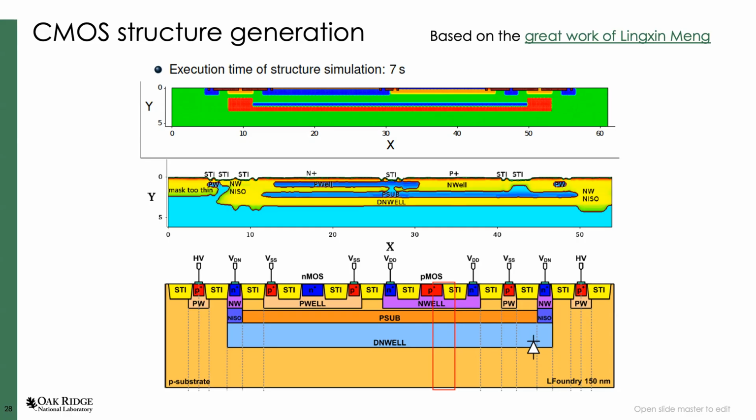So we said, okay, we can drop a bit of complexity by going to the device editor. We wanted the electrical field profile and such to be really realistic, so we still reuse the same doping profile, which is something we knew we could extract and paste into the device or the structure. So we just have a text file at the end that tells, okay, the n well is this value as a function of depth.